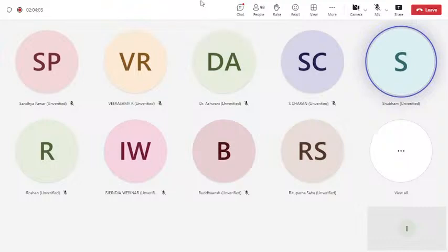The flow will depend on the temperature as well, at what temperature the nozzle is kept, and the bed temperature. It depends on what the minimum temperature is at which the filament can extrude. It is different for different materials.